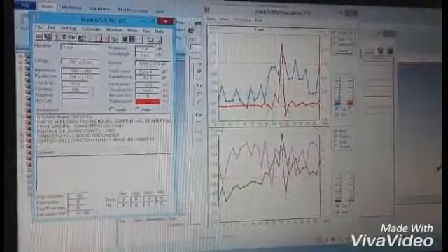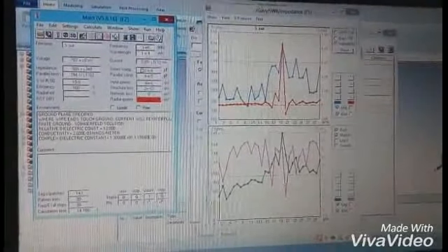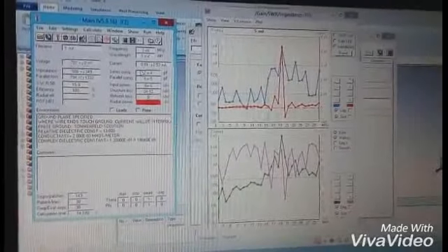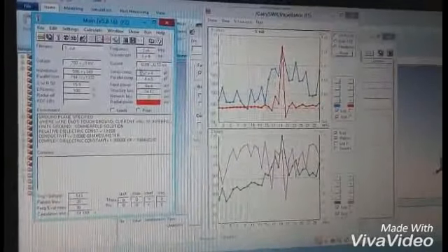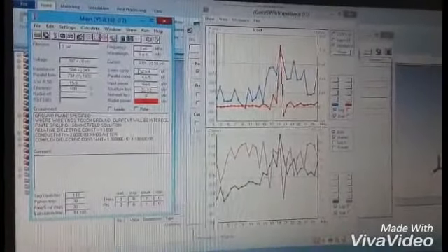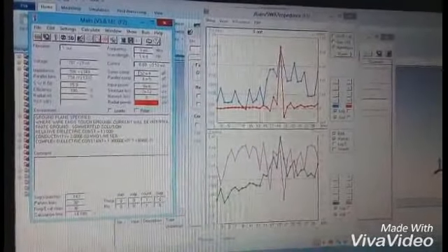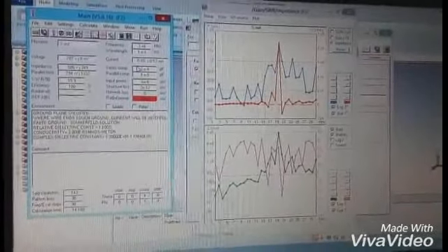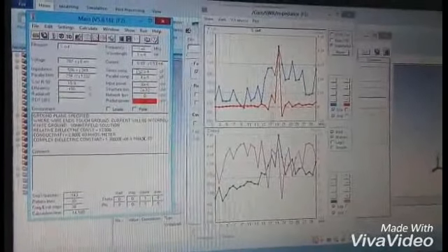From the main window, we can infer that the amount of voltage produced in complex range is 707 plus microvolt, and the impedance obtained can be seen in the table, and the current obtained is around 0.89 milliamp. For a single nano antenna, we can obtain 0.89 milliamps of current.